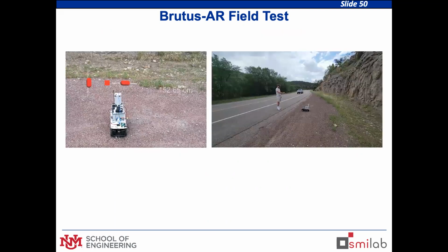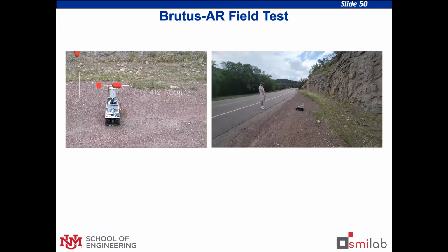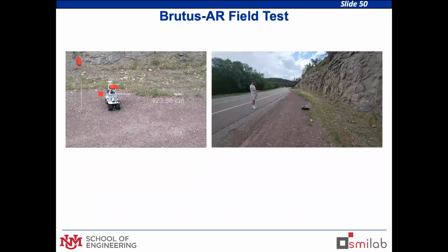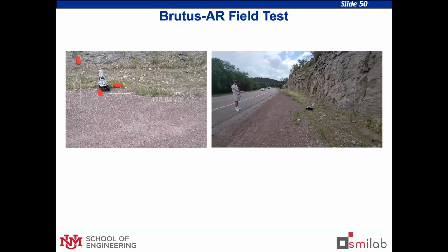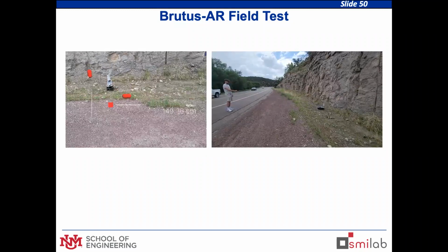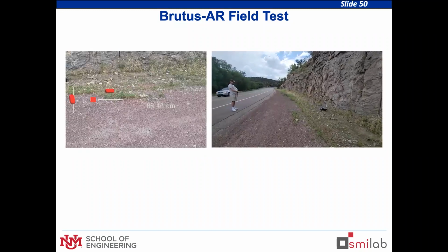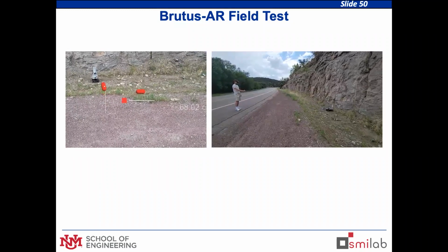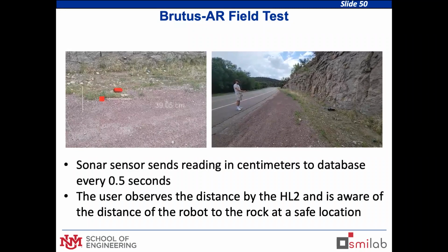You see Elias here is not so safe. So I hope I don't get in trouble. But after we did this, I said, you shouldn't be there because you're very close to the line. So when we incorporated the laser, he went to the other side of the road, so that way you are not exposed to the traffic there. But as you can see with the laser, he can know how close you are to the wall. And you can actually make the robot stop at the distance, which he did at, I think, 20 centimeters. So you always have the same energy when you interrogate with your tapping.